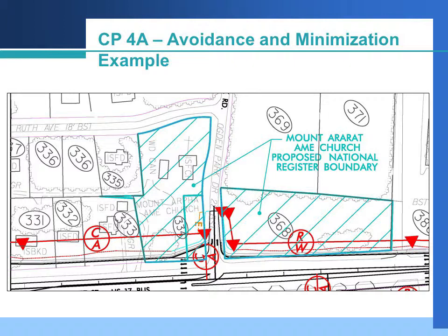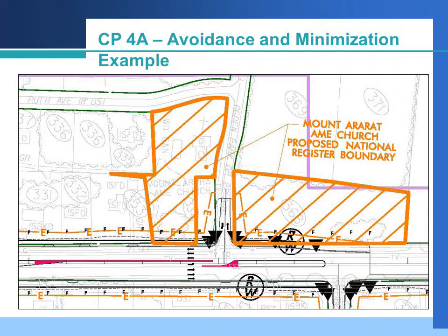As noted, impacts around the interchange were avoided or minimized by pulling in ramps and loops. As a result of modifying the ramp in Quadrant A to an angular exit, a full exit lane was no longer needed in front of the church property. In addition, the storage length for the right turn lane between the 2 historic boundaries was reduced, and control was pulled in along the L line. Through these minimization efforts, impacts to the historic property were reduced by approximately 1/2 acre.